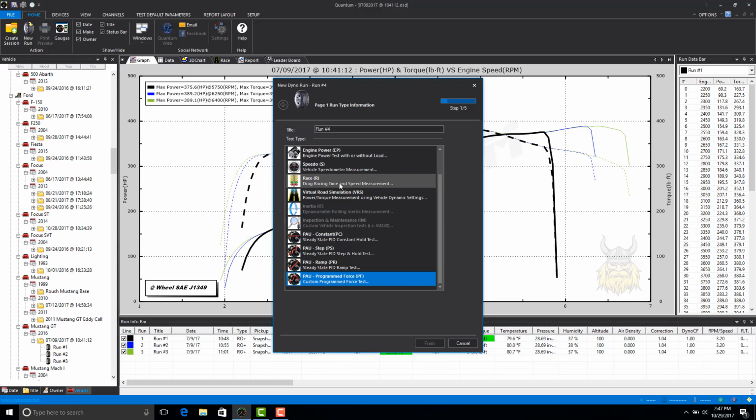If torque falls off in a non-linear way, you're not effective when you try to do it with interpolated load, because interpolated load is linear, either linear up or linear down. So it's assuming more of a straight line build or fall off of torque. And if your torque doesn't build or fall off that way, then perhaps the custom test is for you. And so with that, it concludes the overview of the load or test types in Quantum.